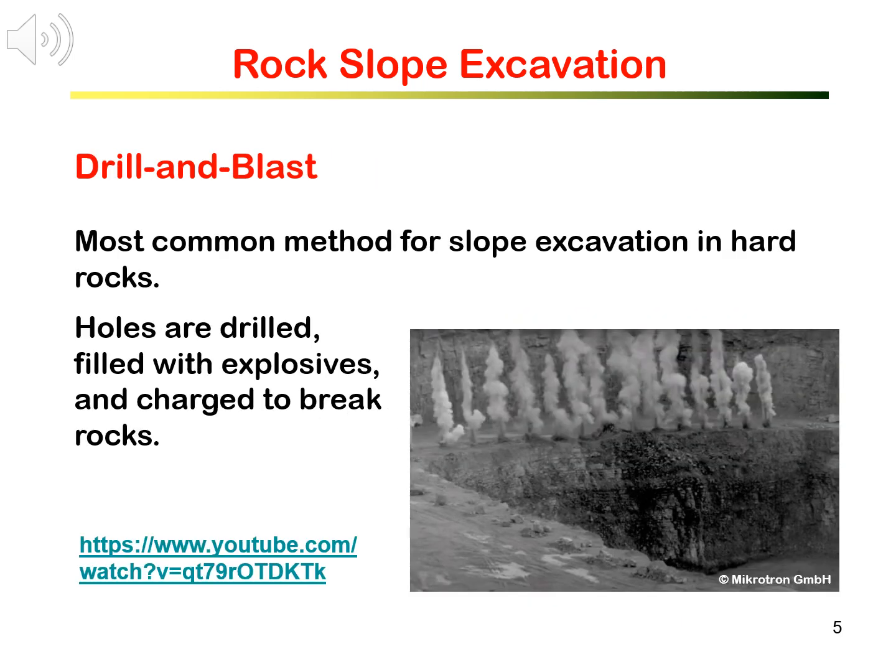The most common method for rock excavation is drill and blast. Drill and blast is used for all types of rock excavations, for slopes, for tunnels, and for mines, particularly for hard rocks. The typical drill and blast procedure for rock slope excavation is first to drill the holes as designed for the slope.